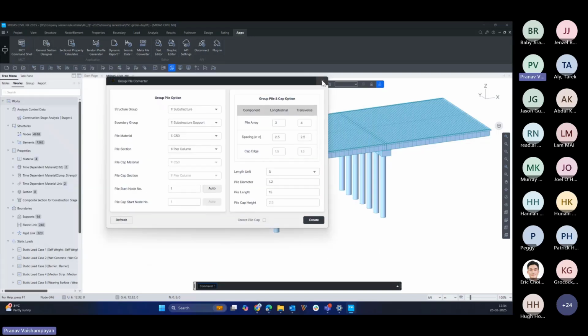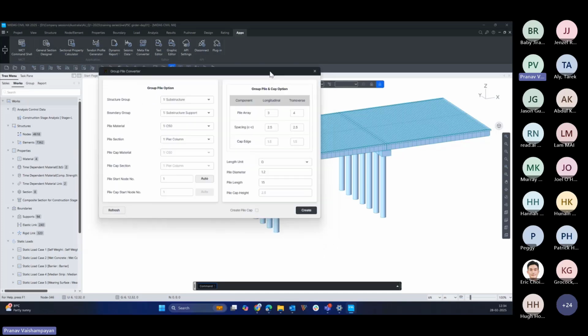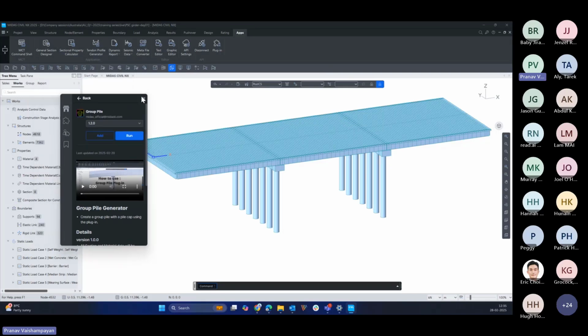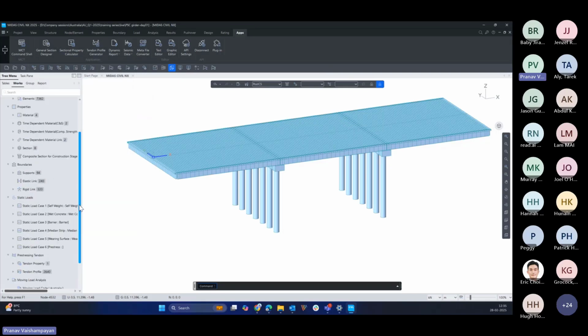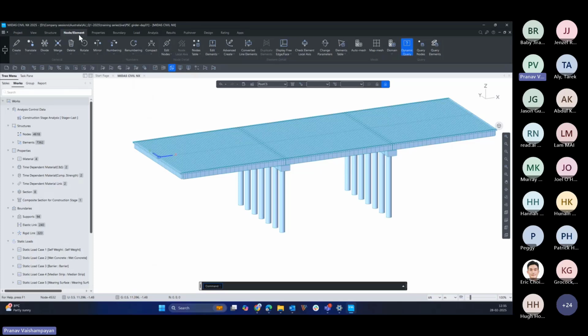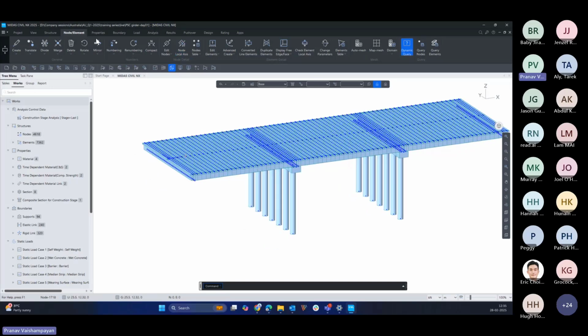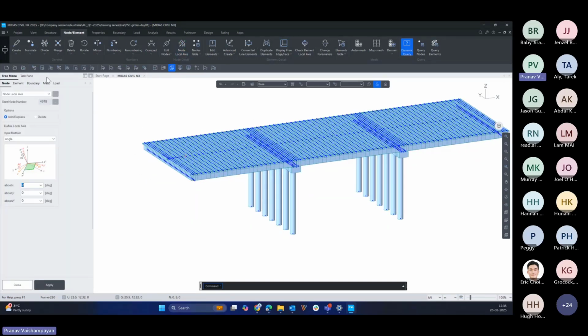Okay, but before we enter this plugin, an important part for this plugin is it needs to have the local coordinates at respective nodes. Right now, we have not defined any local coordinates. So let's do that first. So let's go to node element. Go to pre-processing first, because we need to assign the node local axes. So node element, node local axes, using single select the bottom nodes.